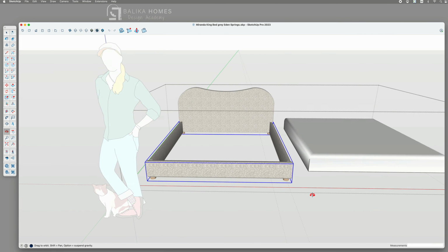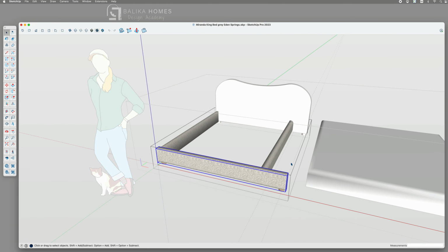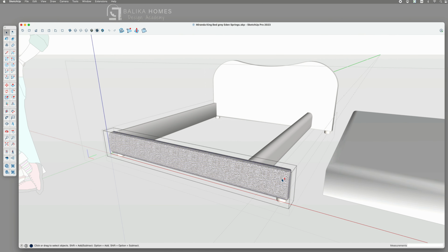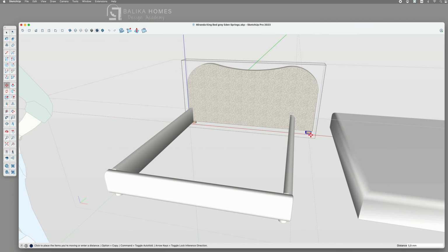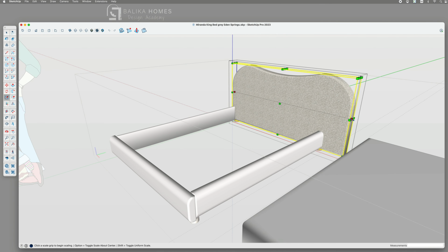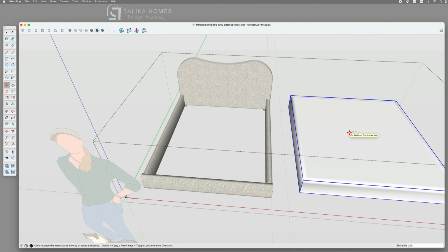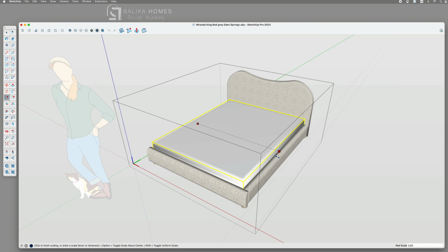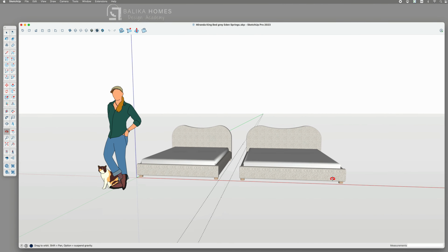Instead of relying solely on the scale tool for the entire group, delve into understanding how the furniture piece is constructed. Experiment with moving individual objects or lines and surfaces. Sometimes it's a matter of strategic combinations of those. In my experience, the aesthetics of furniture are often better preserved this way instead of scaling the entire group as a whole. Hope this little tip will help you in rethinking your process when it comes to adjusting furniture to a different size.